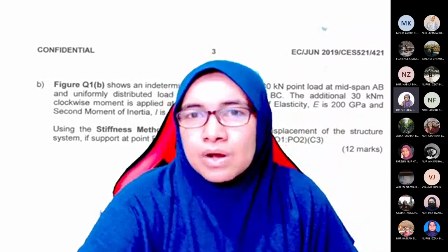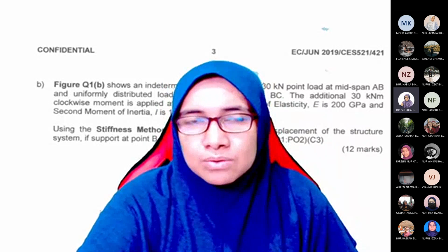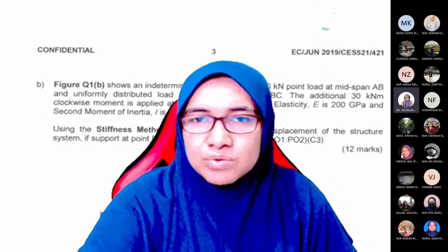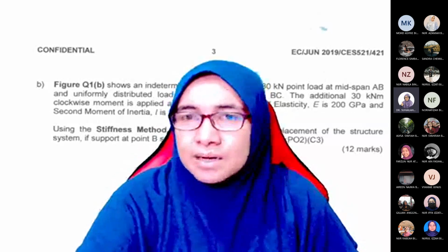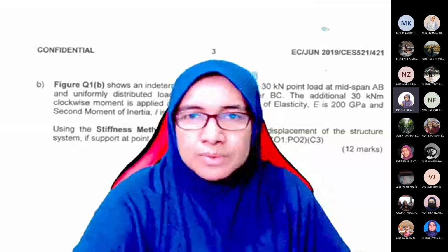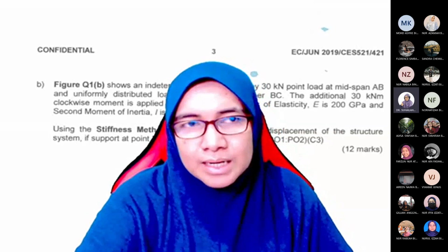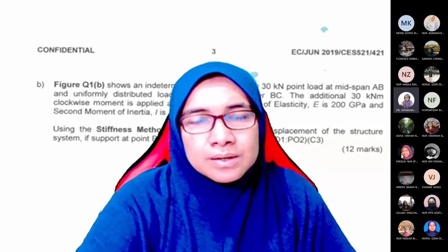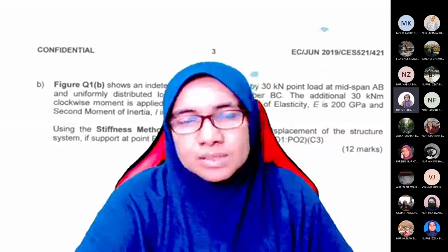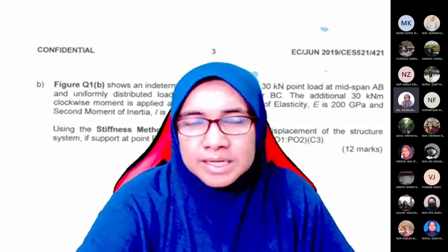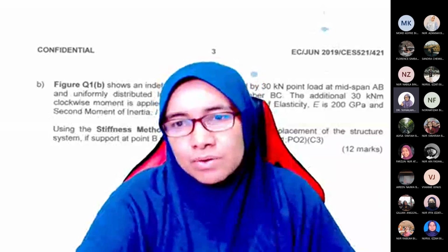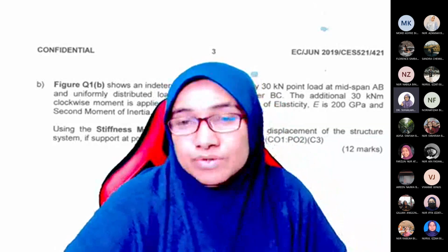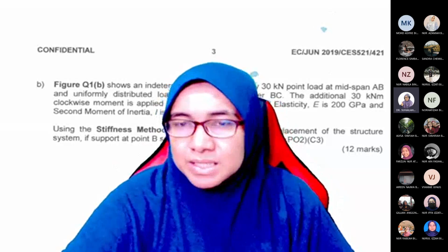So what we need to continue is to focus on how we can analyze the element and global stiffness matrices using the formula that has been derived. The procedure will be the same as what we learned previously in truss. We will start with identification. We have to label all the degrees of freedom, according to unconstrained and constrained. For beam, it is a bit special.